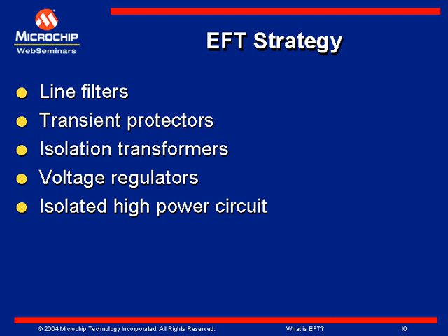Another possible thing is you use transient protectors or use an isolation transformer. Particularly, if you use ferrite iron core transformers, then most of the time you may not have any issues with electrical fast transients, because those big transformers act as a filter. They cannot transfer this high frequency signal. They just pass a 50 Hz signal, but they will definitely block such a high frequency signal, and that way it itself acts as a filter to remove all the noise.